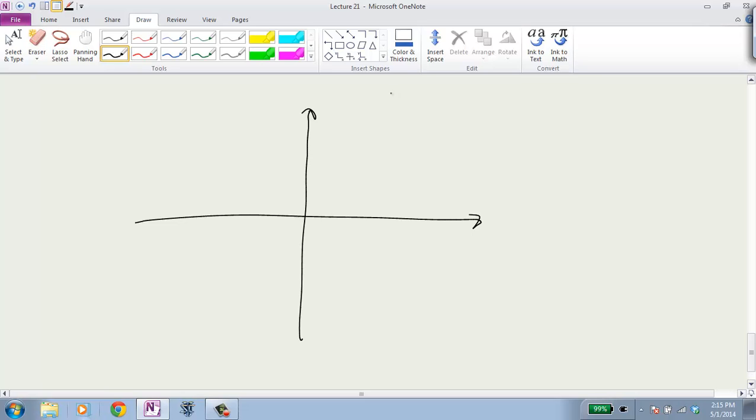Let's say this is a Laplace domain, so it's continuous time. And we found that the poles are in the left half plane. The signal is causal. You may also notice I always put poles and zeros in conjugate pairs. Any real system will have that behavior.